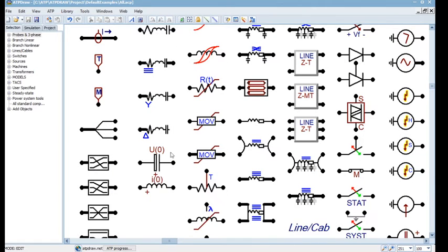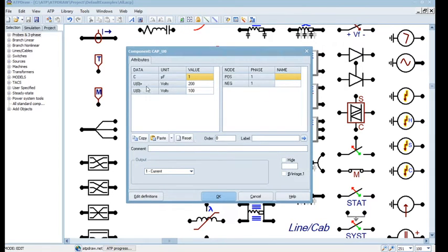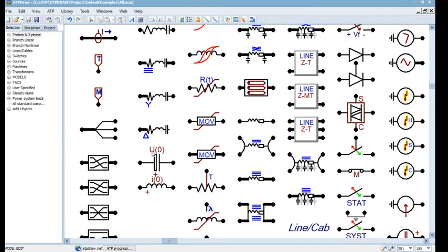Fine. So there are some elements corresponding to capacitors and inductors, wherein you can pass initial conditions as well. For example, let me open it. You can specify the positive terminal voltage and negative potentials here. And for an inductor, you can specify the initial current. Though they have mentioned U0, I0, it doesn't mean that you need to start only at t equal to 0. This just gives an indication that an initial value can be passed, but it can be passed at any time.